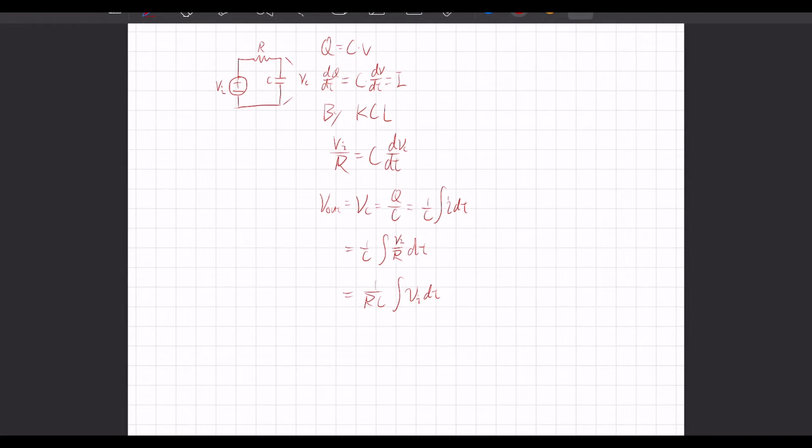So according to the amplifier formula, V out equals 1 plus R2 divided by R1 multiplied by V in. So a circuit with R2 divided by R1 of 9 is needed. After combining the two circuits, we can get the circuit part we need.